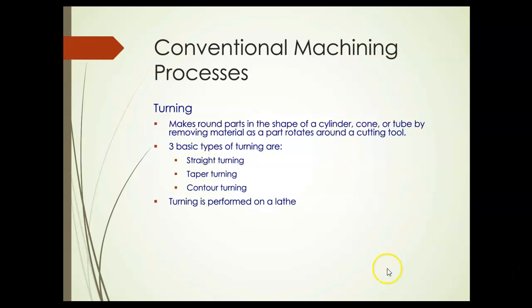All of these are turned on a lathe, and the main thing here that I want you to take away from this is that your part is actually rotating and your cutting tool is moved and pushed through the rotating part in order to cut and make the shape.